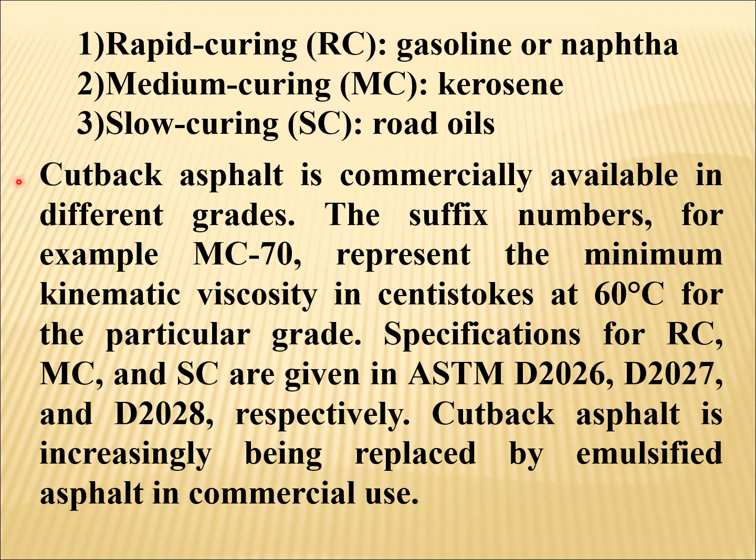Cutback asphalt is commercially available in different grades. The suffix number, for example MC70, represents the minimum kinematic viscosity in centistokes at 60 degrees centigrade for the particular grade. So here this 70 is basically representing the minimum kinematic viscosity in centistokes at 60 degrees Celsius.